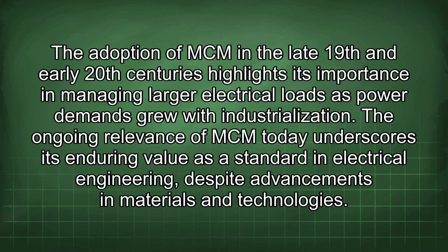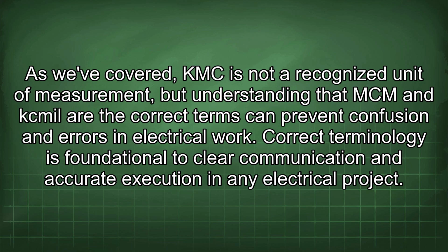The ongoing relevance of MCM today underscores its enduring value as a standard in electrical engineering despite advancements in materials and technologies. As we've covered, KMC is not a recognized unit of measurement, but understanding that MCM and kcmil are the correct terms can prevent confusion and errors in electrical work.